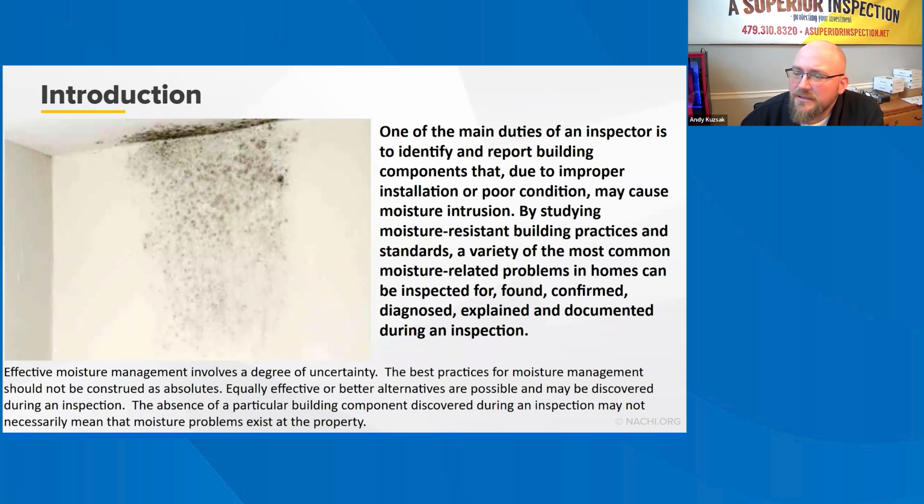Understanding building methods and techniques is essential for inspectors. Defective or improperly installed components can lead to moisture-related problems. Moisture intrusion can cause structural damage and threaten occupant safety, and if water penetrates a building, it should be allowed to exit. Education on the best building practices is crucial.